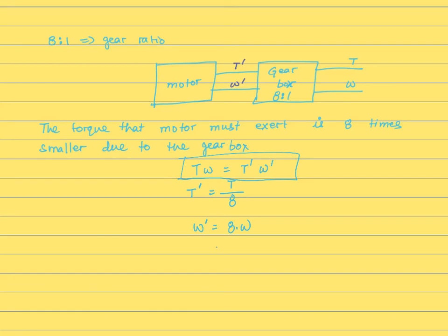We calculated omega as 27.78, which gives you 222.24 radians per second. And with that, we will be able to find K phi, which is 600 volts divided by omega prime, and that gives you 2.7. So that's the first part of the question.